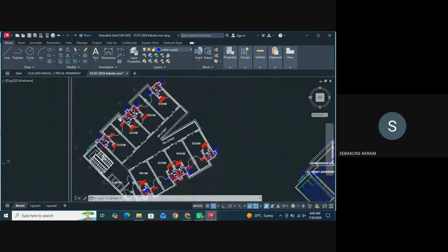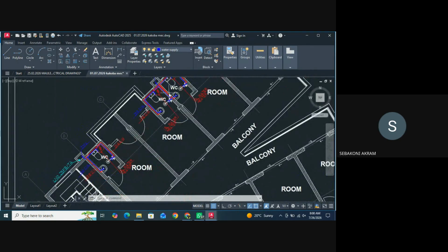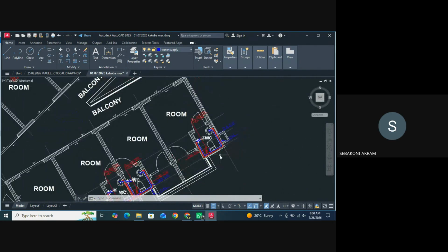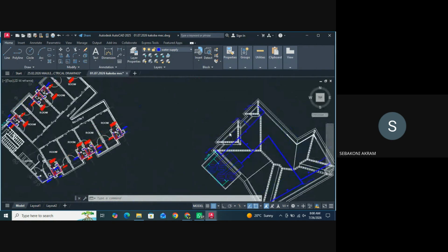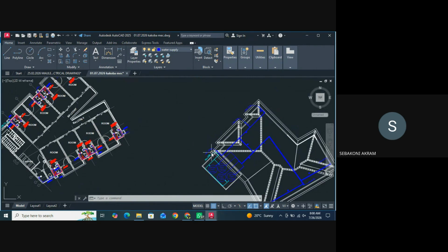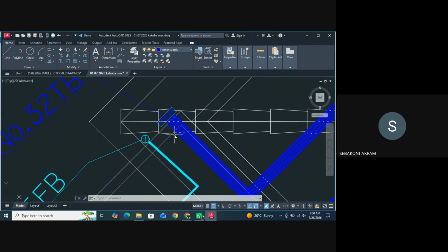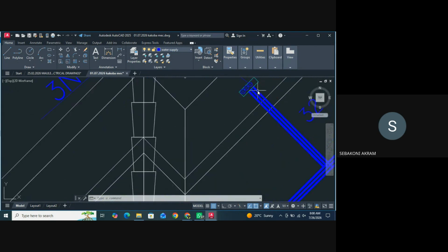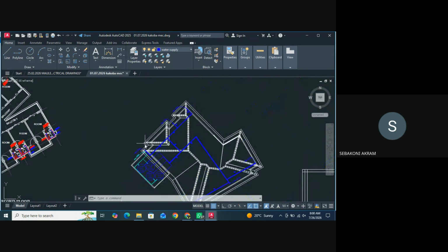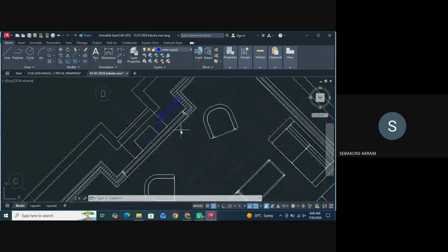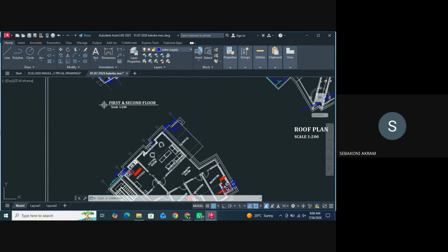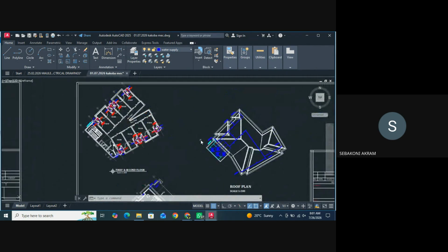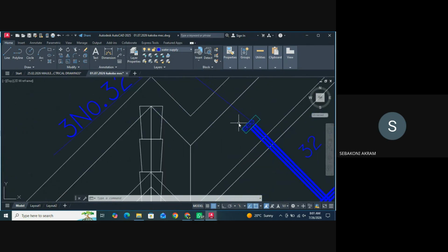Because you think from each floor, you're having 1, 2, 3. Okay, you see, the 1, 2, 3. And at each point we are bringing the what? The 4 pipes. Here we brought 3. Why? Because the upper floor, there is no supply here. Are you seeing anything being supplied at this point? No. So here we bring 3 because there are only 3 floors down.